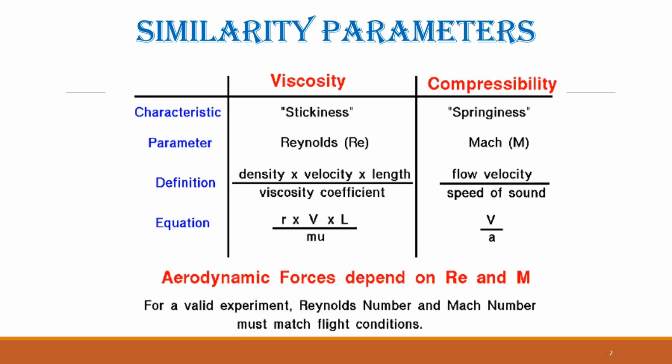This interaction between the moving air and the object generates aerodynamic forces. The magnitude of these forces depends on several important factors, including the shape of the object, its speed, and the mass of air flowing past it. In addition, two key physical properties of the air significantly influence these forces. Viscosity, which describes how sticky or resistant to flow the air is, and compressibility, which describes how springy the air is and how much its density changes when pressure is applied.